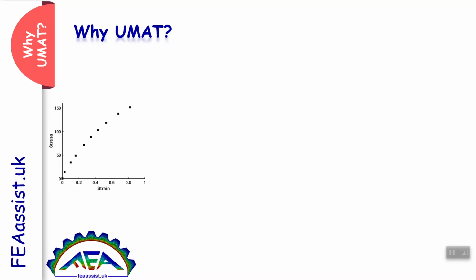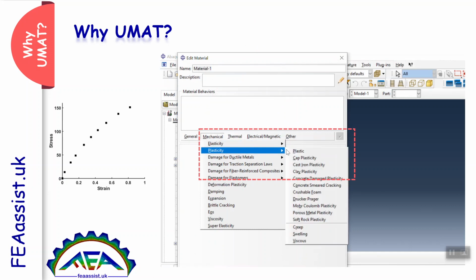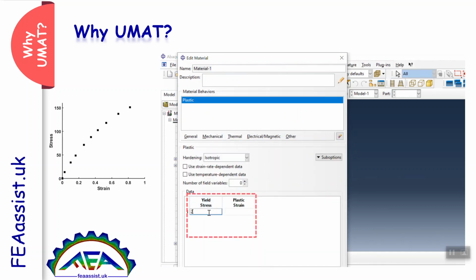The first strategy is that you have some points of your stress strain behavior from lab or from published experiments. You can easily go to Abaqus, to the property, define a new mechanical behavior, plastic behavior, and enter those points like this. This is the simplest way of solving the problem, but it is not precise because Abaqus interpolates between these points and solves the problem in all points.